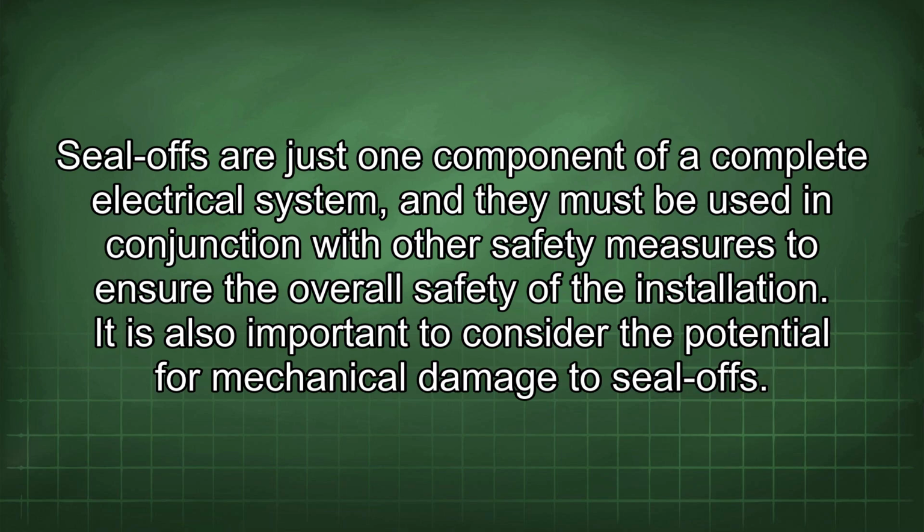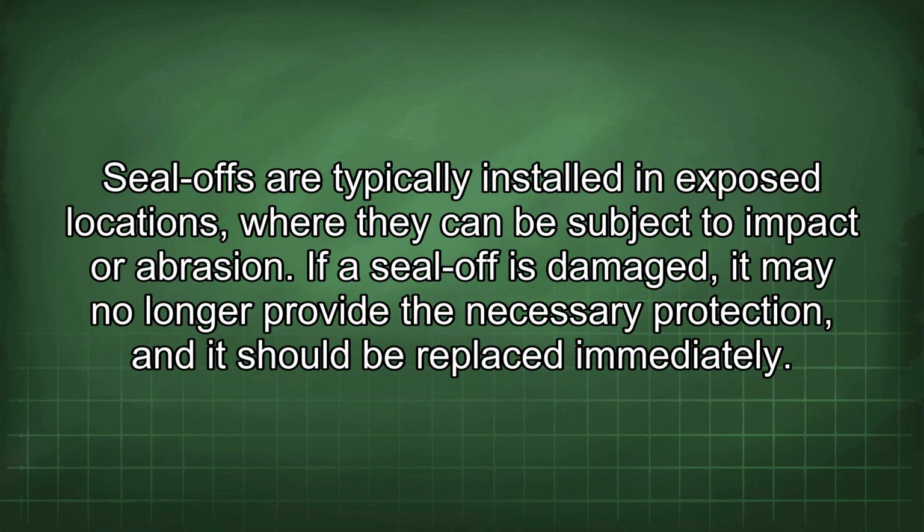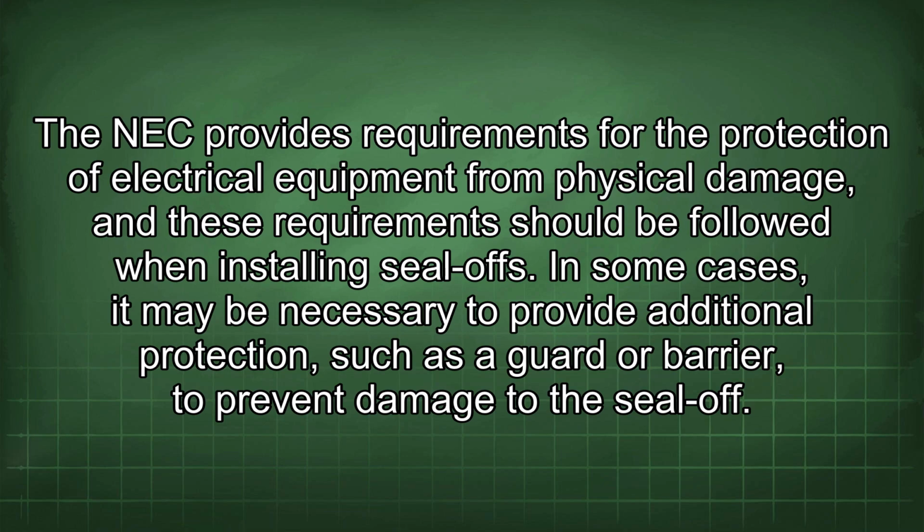It is also important to consider the potential for mechanical damage to seal-offs. Seal-offs are typically installed in exposed locations where they can be subject to impact or abrasion. If a seal-off is damaged, it may no longer provide the necessary protection and it should be replaced immediately. The NEC provides requirements for the protection of electrical equipment from physical damage, and these requirements should be followed when installing seal-offs. In some cases, it may be necessary to provide additional protection, such as a guard or barrier, to prevent damage to the seal-off.